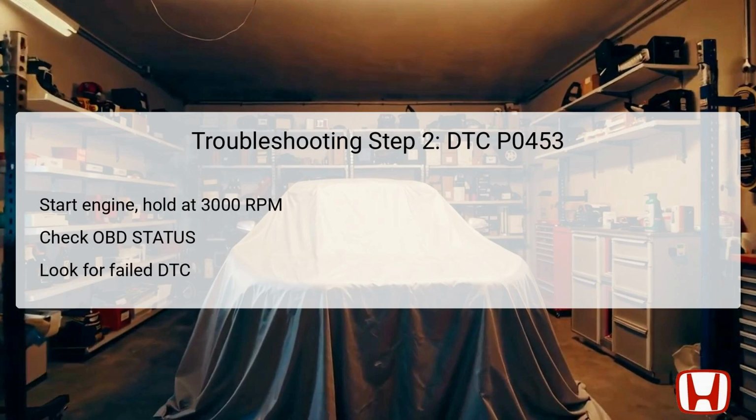As the engine runs, utilize the HDS tool to monitor the onboard diagnostic (OBD) status concerning DTC P0453. If the HDS indicates a status of failed, it means the previously recorded fault can be replicated under the same conditions, indicating a malfunction that must be addressed.